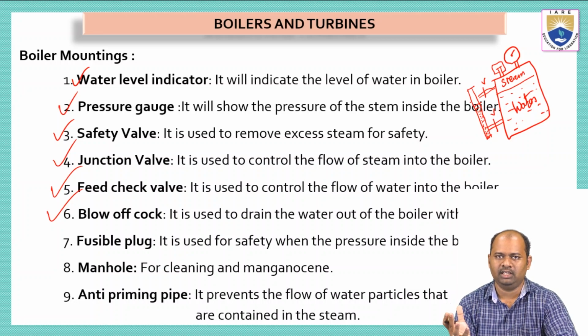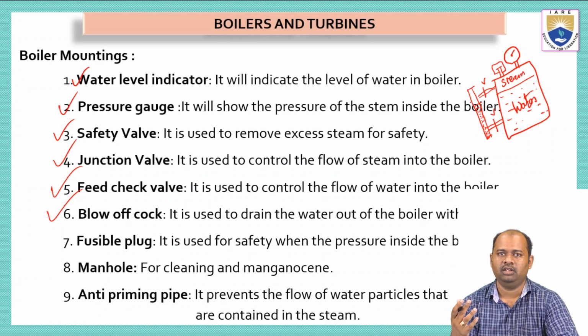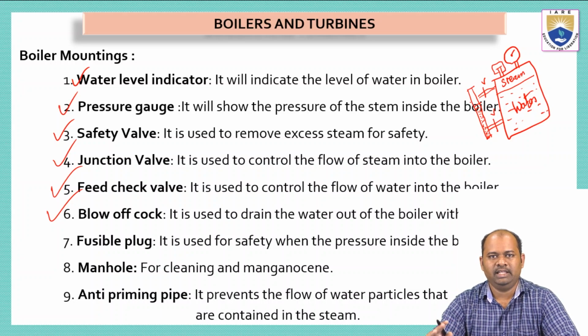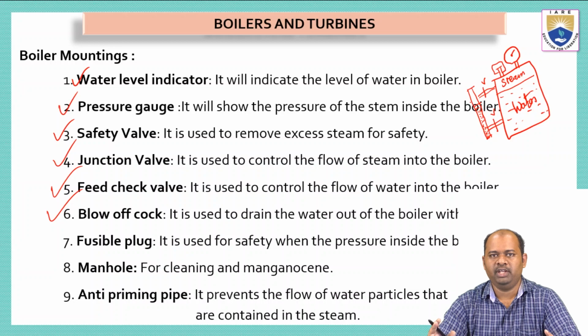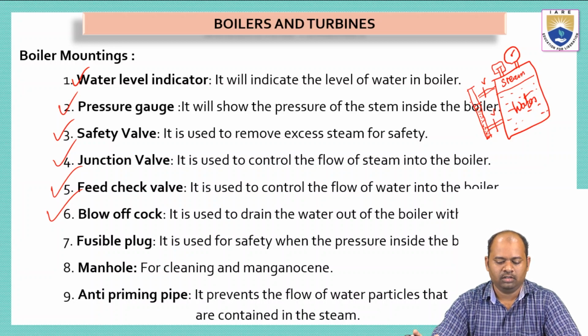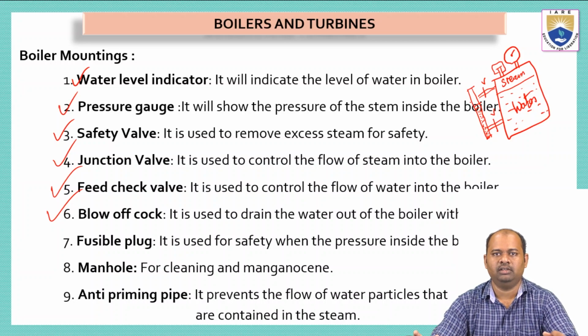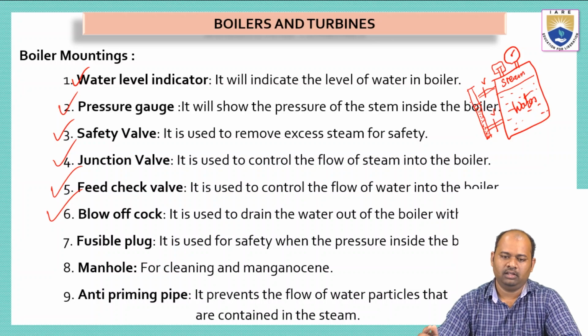Due to the formation of scaling, there are many disadvantages, like heating cannot be done properly, or the steam which is formed may not be collected easily because of the scaling. We know that scaling is where the salts present in the water get deposited in the tank due to heating. In order to clean the tank, we should have an opening at the bottom of the tank. That is called the blow off cock. This is a valve that is opened, and the wastewater will be collected through it.